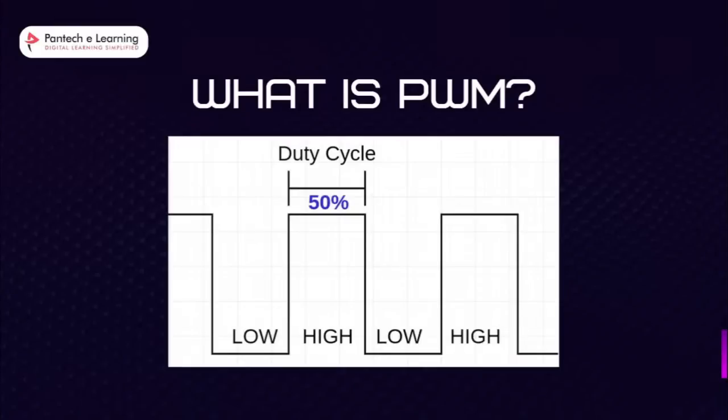Here we will create an LED dimming project in STM32CubeIDE by using the STM32 HAL API, which is nothing but the hardware abstraction layer. We will control the brightness of the LED by generating a PWM signal using the timer 2 peripheral of this particular STM32F446RE microcontroller. Actually the hardware part is very easy. We just need to connect the LED, ground and some pin. Here I am going to take the A0 pin, which is from analog, right?